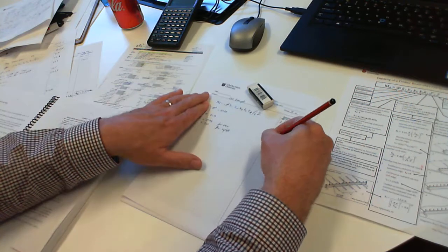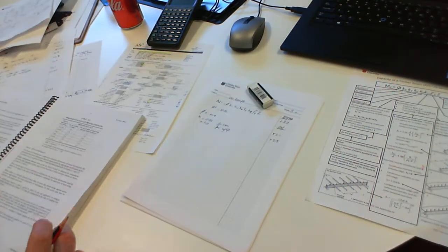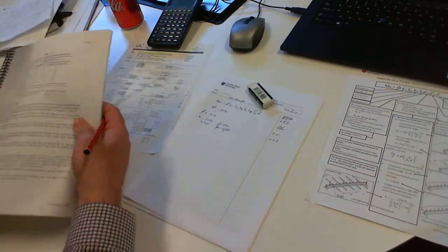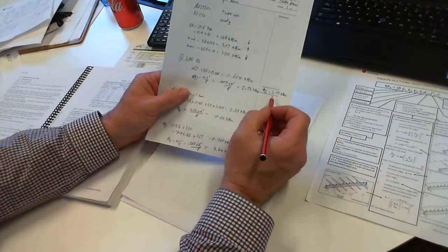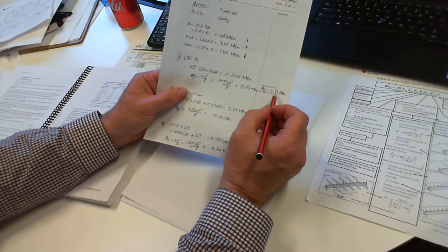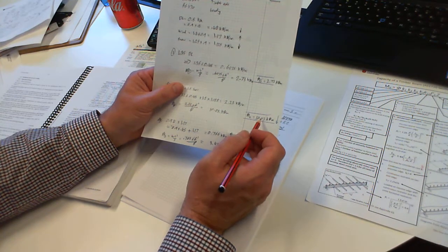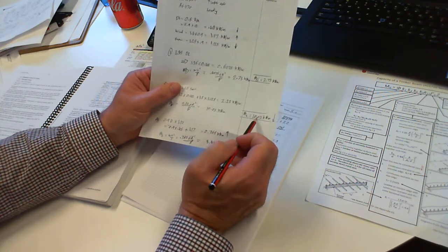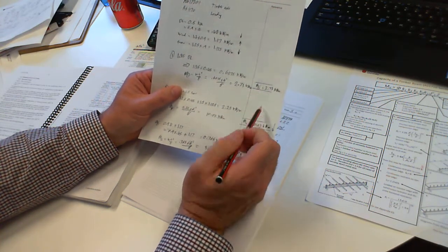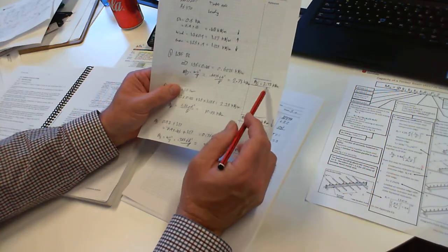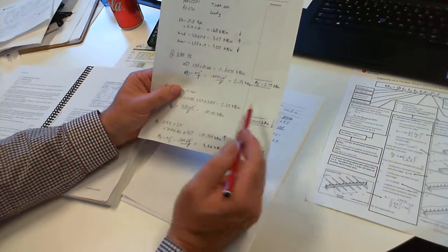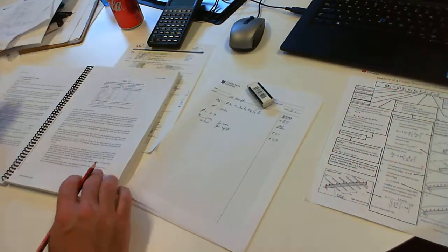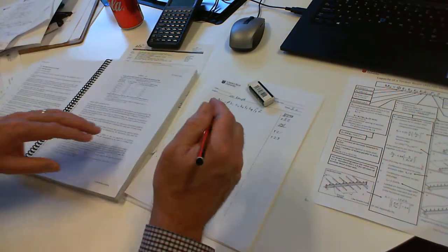And that's table 2.3. Now I should point out at this time that we remember back on page 1 we had the moment for the dead load only was 2.73, and the moment for live load and dead load was 10.02. For the permanent load only, the K factor is 0.57. So if that was anywhere near that, I would be going and checking to see which one of those is more severe. Now, if that was anything above 6, you should be checking that. I know in this case that because that is way more than that, this is still going to govern, so I'm not going to go any further. Okay, that's K1. Let's do K4.